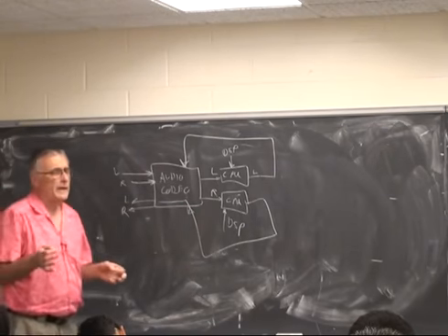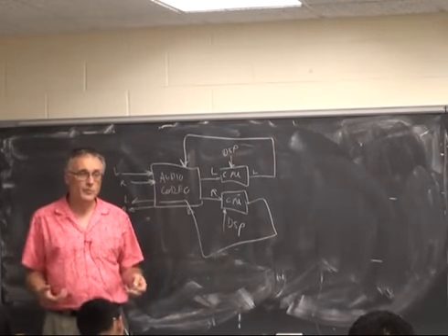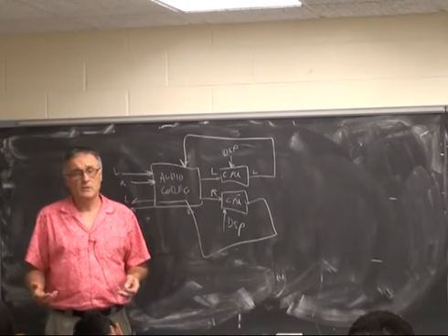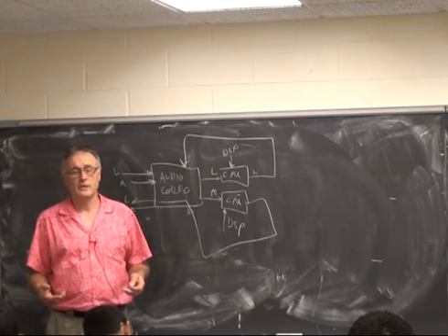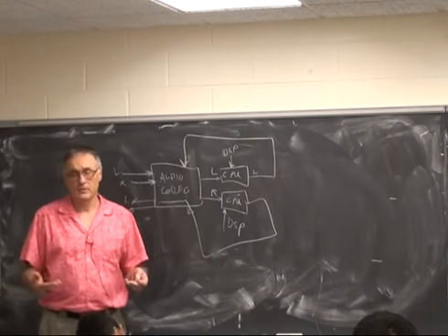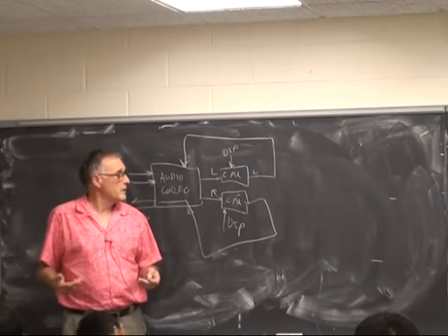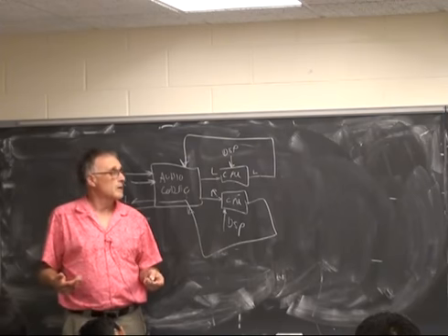So this is really kind of embarrassingly parallel computing. It's computing where we're going to use 2 CPUs. That's to get used to implementing multiple objects on the FPGA. They're going to be the same CPU, 2 instantiations, each one running a separate copy of the code.